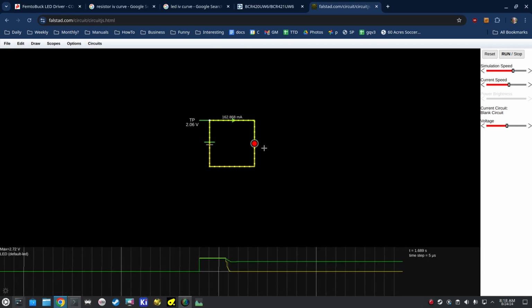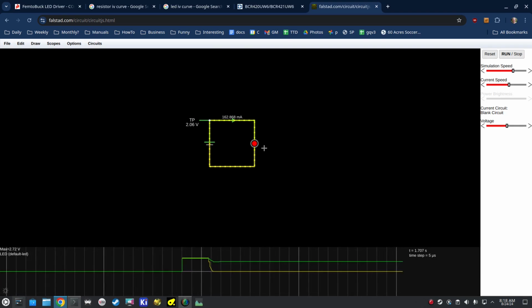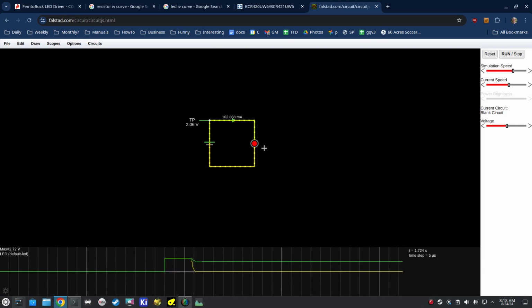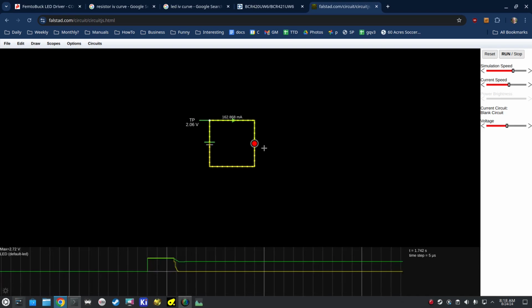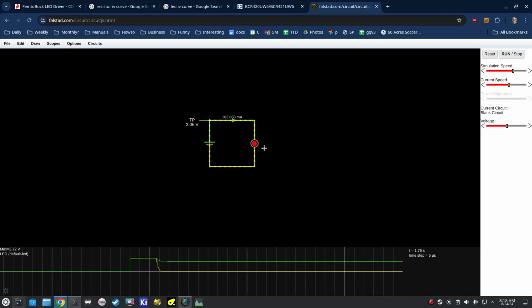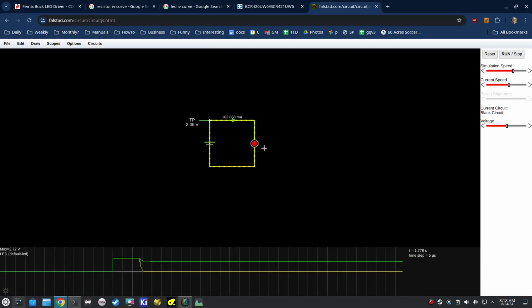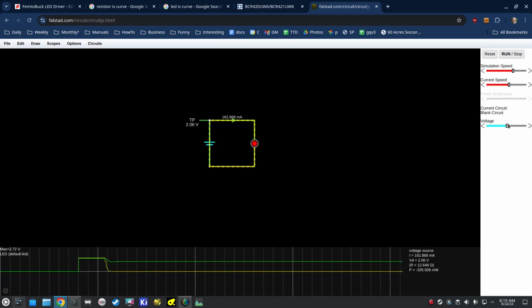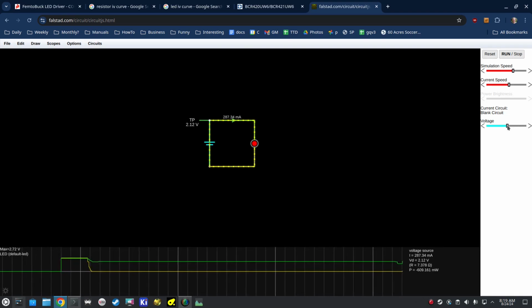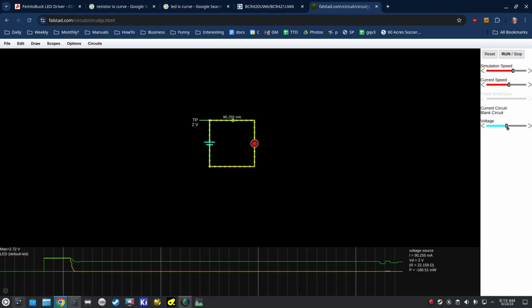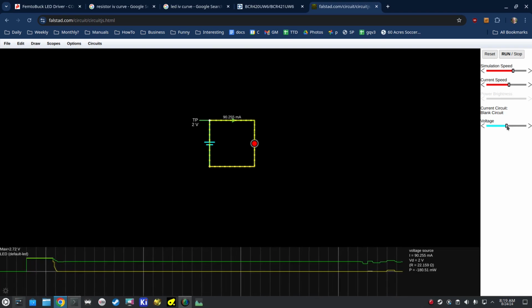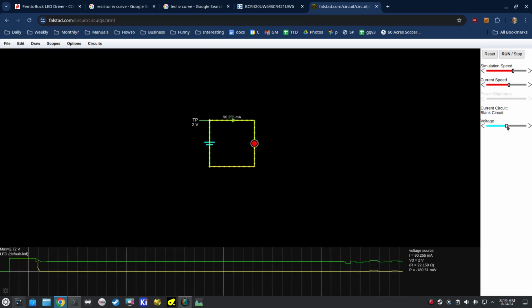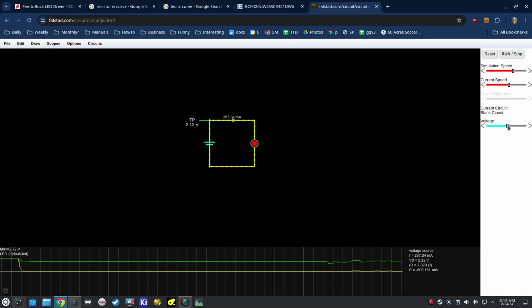At 300 milliamps, they actually run pretty hot, which means you're using up a lot of energy in heat, and also you might be melting things like foam that the LED is connected to. So I don't recommend driving these things at their max rating, but instead driving them at less. So between 150 and 200 for a 300 will still give you plenty of light. You might not even be able to tell the difference, but significantly less heat.